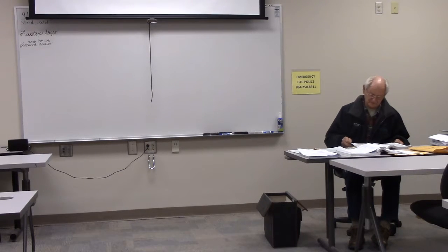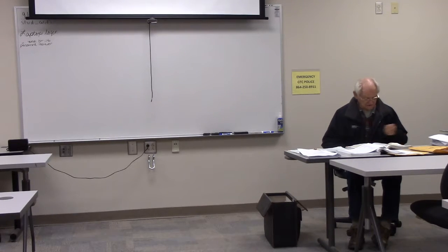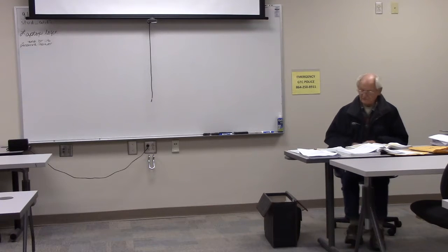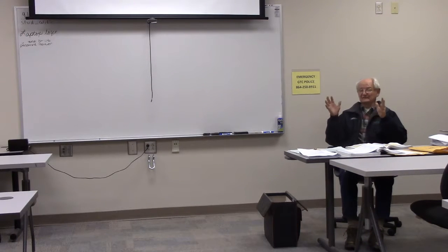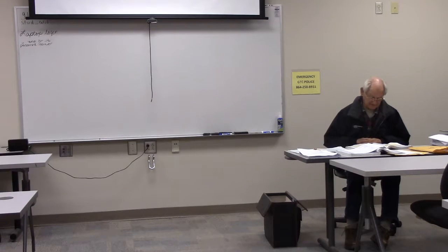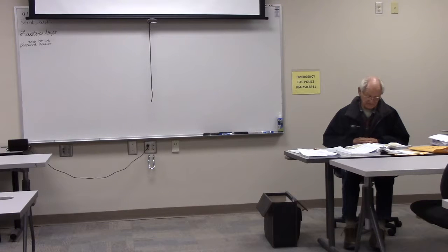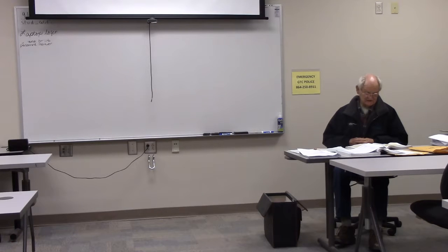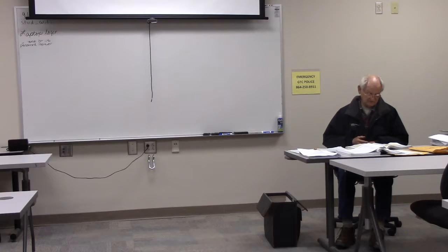You don't have your books with you, and I understand that, but you could look on here and see that. And then the engineering scale, which you would use mostly with the civil portion of the job, like the big lengthy thing. The engineering scale is used mainly for land measurements on site plans, which means the scale must accommodate very large measurements. The engineering scale is set up as multiples of 10, and the measurements are taken in decimals.